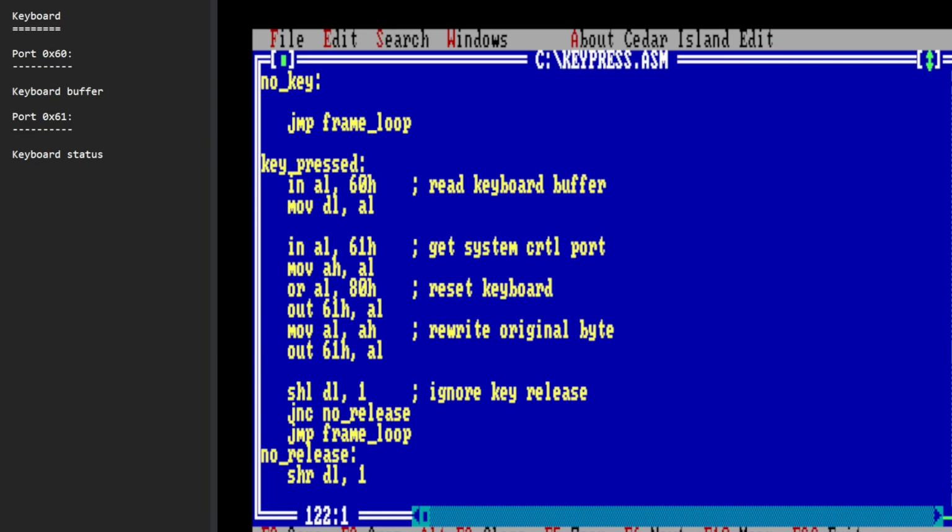And that finishes off our handshaking routine. So it's a little bit strange, but this is what the keyboard will recognize. So now we're free and clear, we can take a look at our scan code and see what key was pressed. And I made the arbitrary choice to just ignore key releases. I only want to know when the key is pressed.